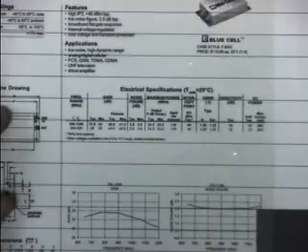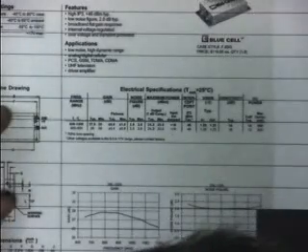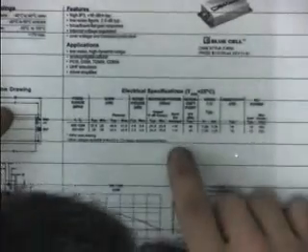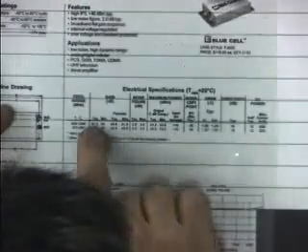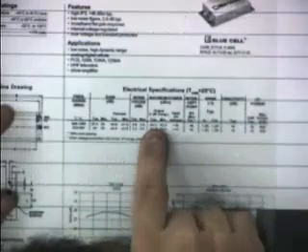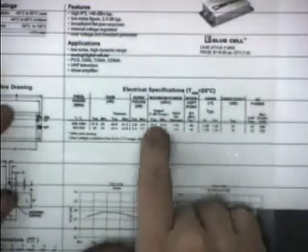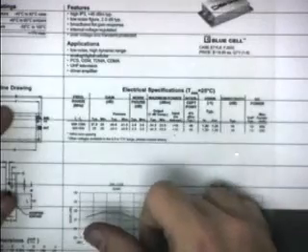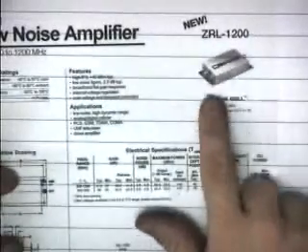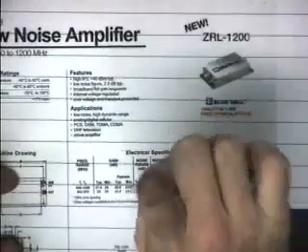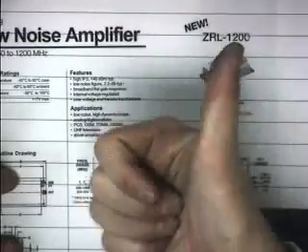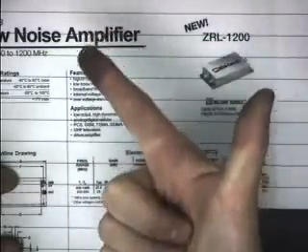You're not even getting as much gain, I don't think. Well, no, the gain's not too bad. The lousy maximum power. Notice the 1 dB compression points are about 10 dB less than the previous one. So these really aren't meant to put out a lot of power, but that's okay. You just need to get gain, and you need to get as little noise added as possible.